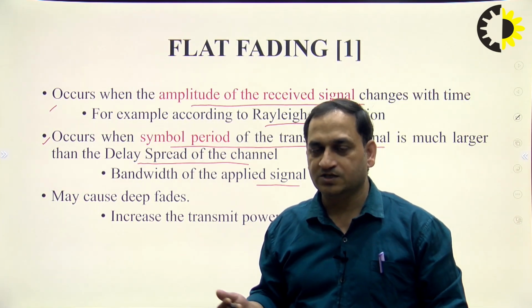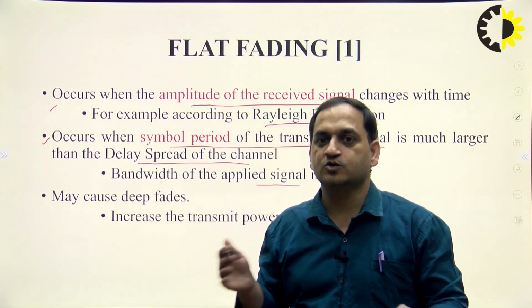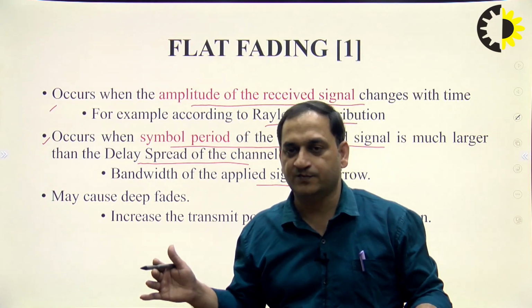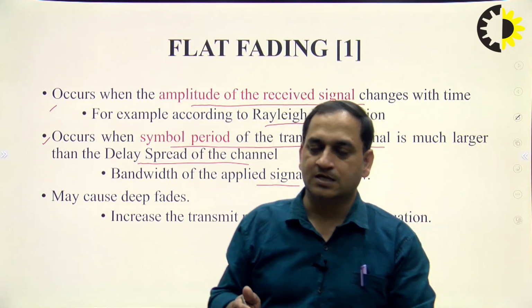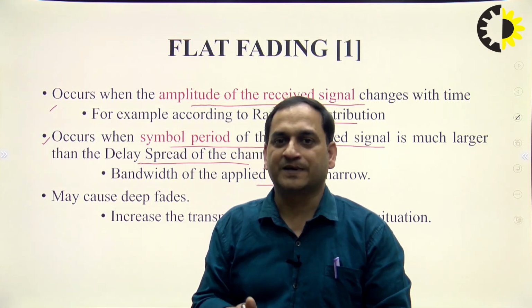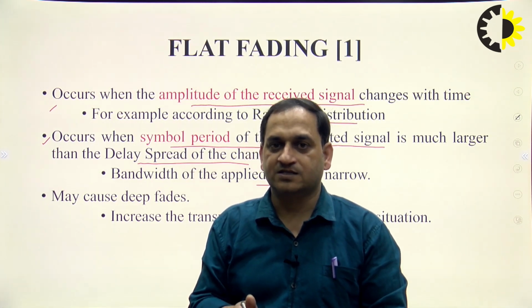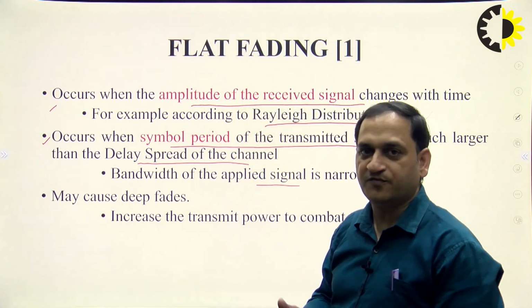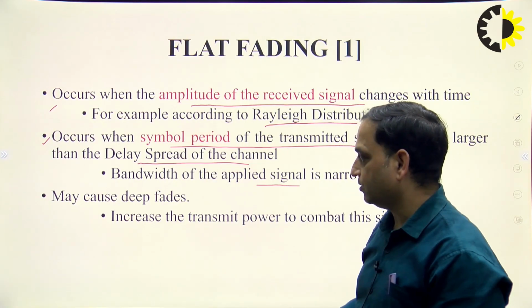So our goal is to reduce that wide band of frequency into smaller chunks. If we can divide this wide bandwidth into smaller chunks, these chunks are called the subcarriers, and these subcarriers are very narrow in bandwidth. So it will be responsible for the flat fading, right?